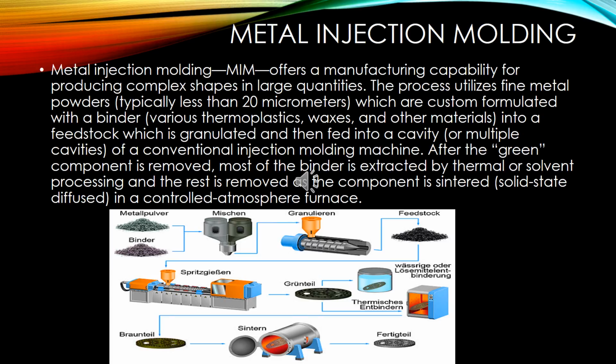Metal injection molding is another process to transform a material. It is a metalworking process in which finely powdered metal is mixed with binder material to create a feedstock that is then shaped and solidified using injection molding. The molding process allows high volume, complex parts to be shaped in a single step. After molding, the part undergoes conditioning operations to remove the binder and densify the powders. Finished products are small components used in many industries and applications.